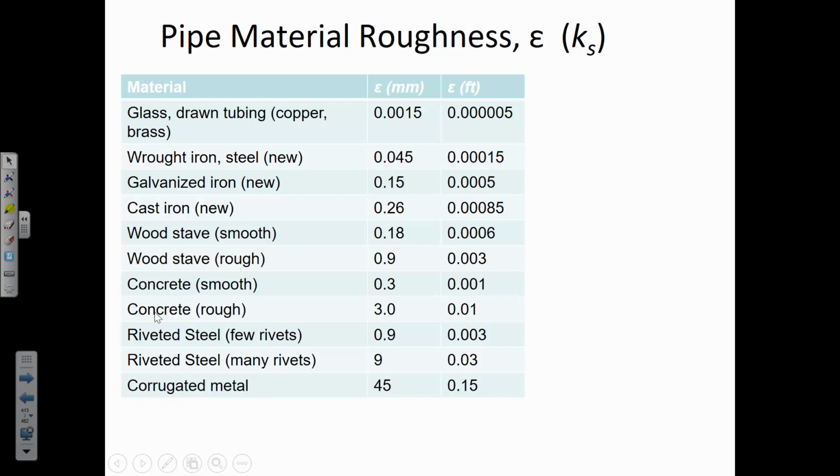And I'm sure some of you have seen a brushed concrete surface before, where maybe they're intentionally trying to make it a little bit more rough to provide traction if it's maybe a steep grade or a surface that could receive some snow and ice during the winter months. So a rough surface maybe would be high enough to have an equivalent roughness of 3 millimeters.